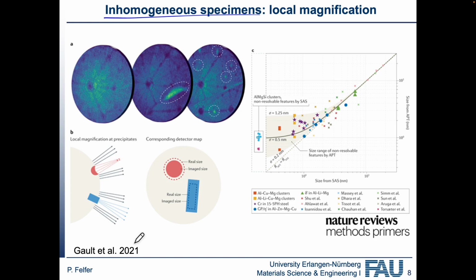And here is actually an example where we have some precipitates, and I believe this would be aluminium and probably some magnesium silicon precipitates in there, and some clusters. And what the effect is, just imagine you've got a specimen and the field necessary is a little bit higher for a precipitate, then of course it will need a larger radius.